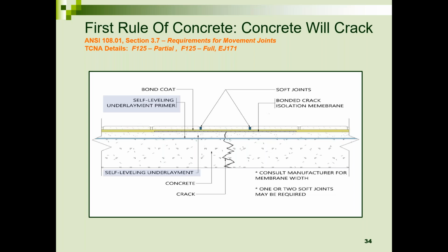Or in the case of an existing crack, again, here's all the components you need to successfully install a tile floor over a crack. And the methods here are utilizing either a partial or full membrane. A partial, you're just covering over the crack. A full membrane, you're going wall to wall. But again, this is very important to understand how to install the tile.